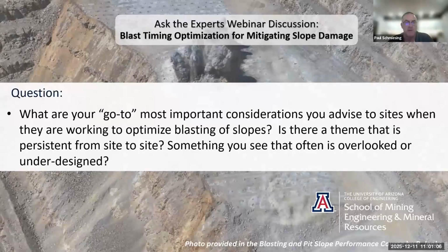So to me, when you do have to do that modified production blast, you're not just throwing away everything you were doing. You keep, okay, I can't do a separate trim blast here, but I'm at least going to deck the holes. I'm going to do some of those. I'm going to pay attention to my direction of recoil.